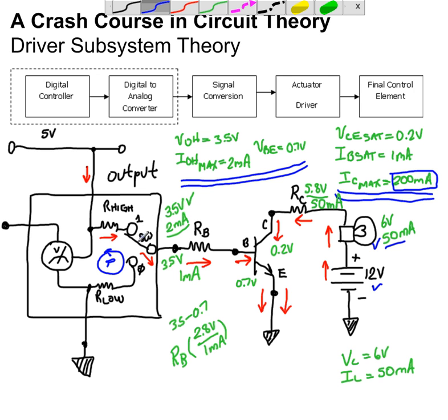You need the information about your microcontroller. You may either get this from the data sheet or you may have to run a few tests to see what is the typical output voltage. And finally, you need to know how much current you need in order to put this transistor into the saturation condition, which will allow the current to flow through the collector. Following this procedure will allow you to calculate the unknown values for RC and RB, and you can have a successful driver circuit to operate any load that you desire.